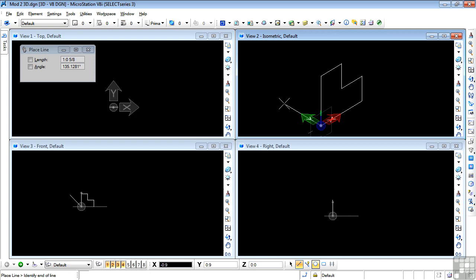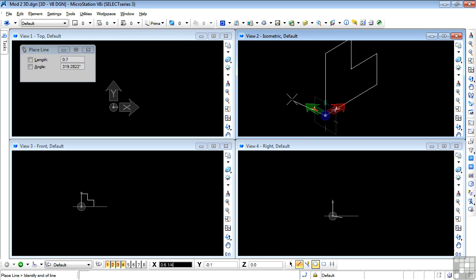So I need another key at the keyboard. The correct key is S for side at the keyboard. Press that, and my compass rotates to essentially a right orientation. I can now enter the dimension for the width of the step block, and I'm going to use 5 again. So :5, there it is there, left click.